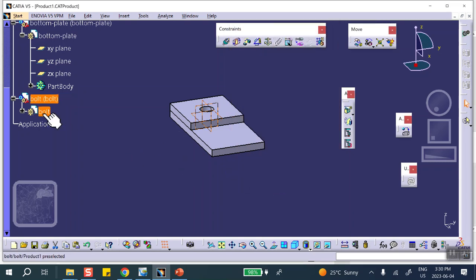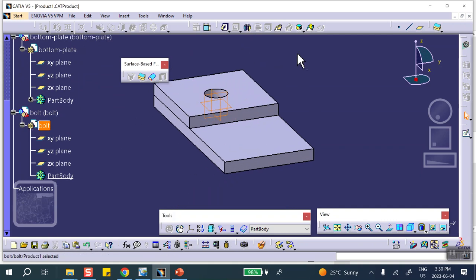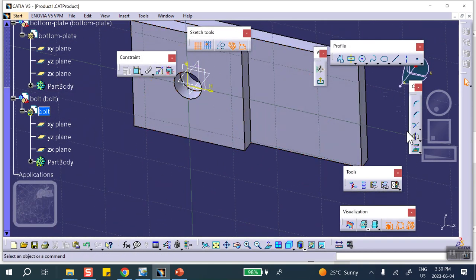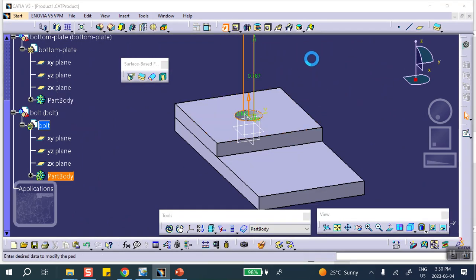And we're going to make it. Now, there are different ways of doing it if I want to be really lazy. So what I'm going to do is on that top plate, I'm going to sketch. Why don't I project that circle? Okay, exit. All right, and pad it.